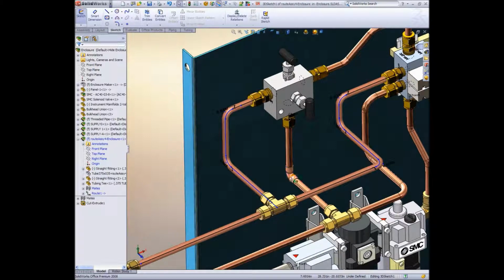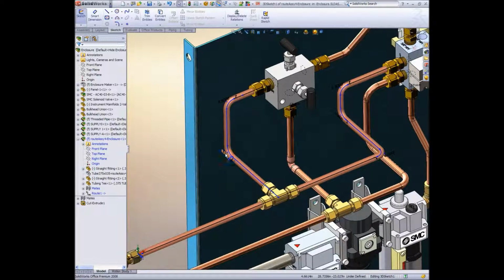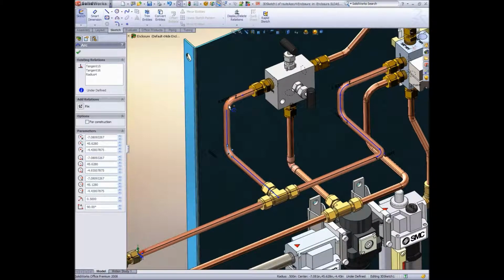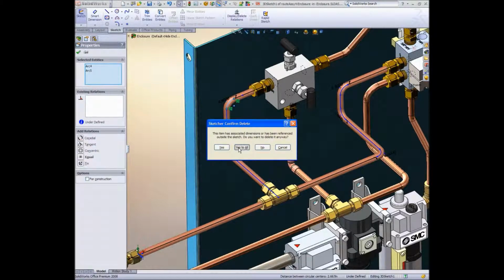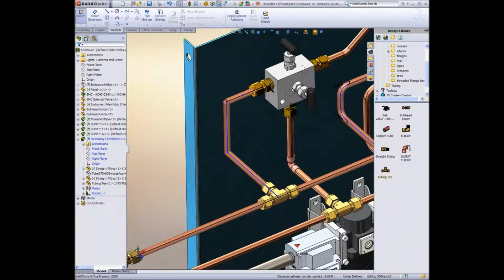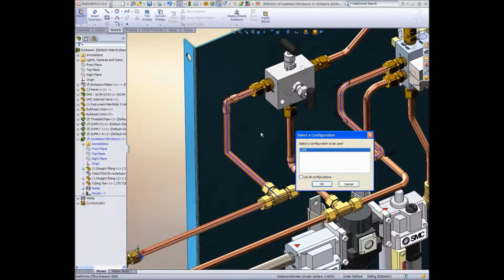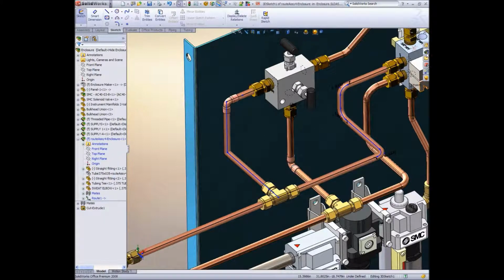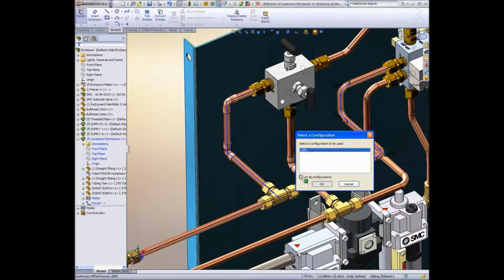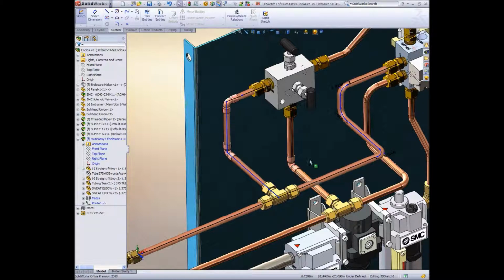Now just to change things up, you'll notice that there are some sweat fittings in the corners. SolidWorks is very flexible, allowing me to use bent pipes, or in this case, we'll just delete the bend information off and use a sweat fitting by dragging and dropping. Place 2 of those into our design. One of the benefits of SolidWorks routing tools is that behind the scenes, SolidWorks is always trimming up the pipes to be the appropriate length for manufacture.